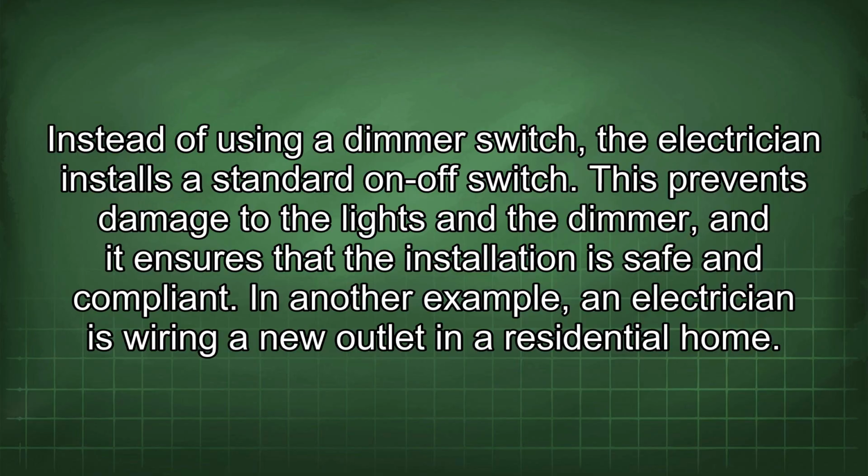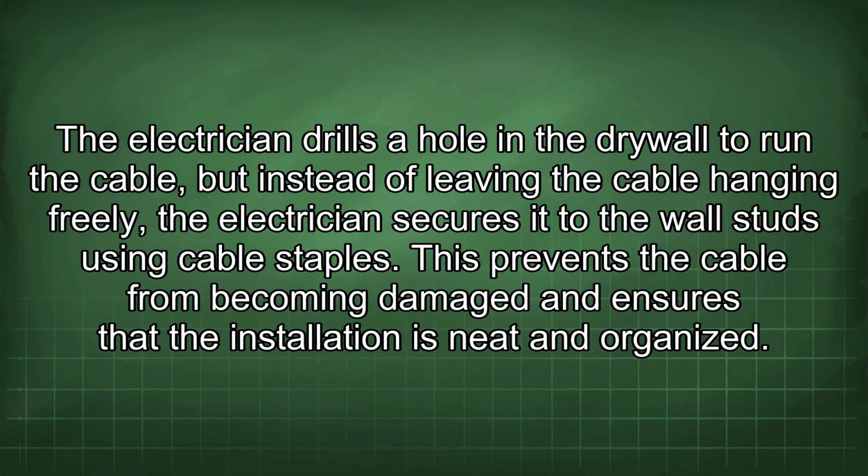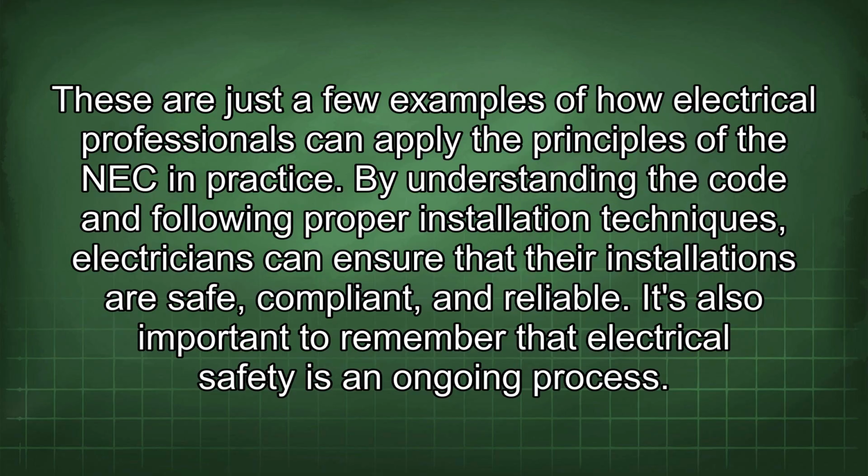In another example, an electrician is wiring a new outlet in a residential home. The electrician drills a hole in the drywall to run the cable, but instead of leaving the cable hanging freely, the electrician secures it to the wall studs using cable staples. This prevents the cable from becoming damaged and ensures that the installation is neat and organized. These are just a few examples of how electrical professionals can apply the principles of the NEC in practice. By understanding the code and following proper installation techniques, electricians can ensure that their installations are safe, compliant, and reliable.